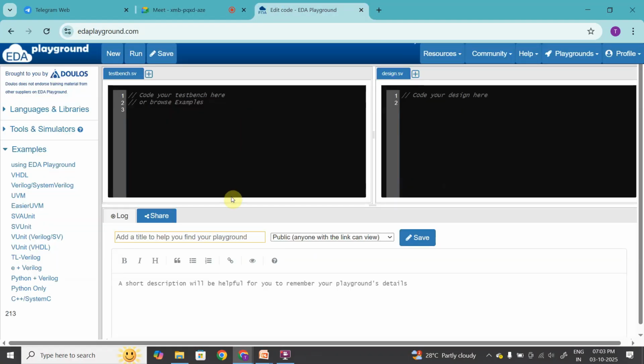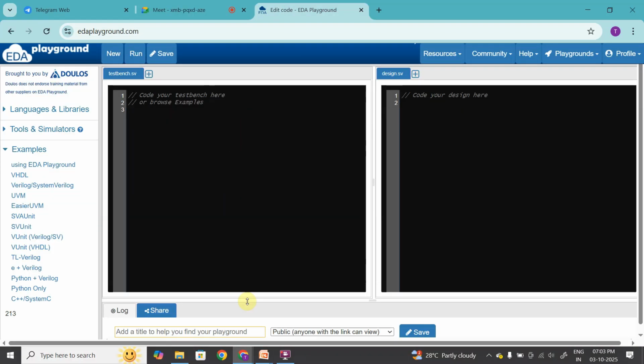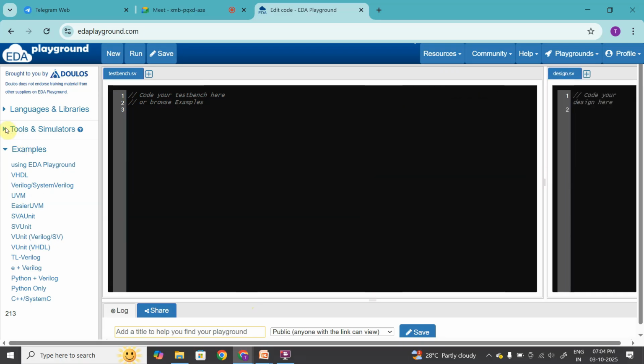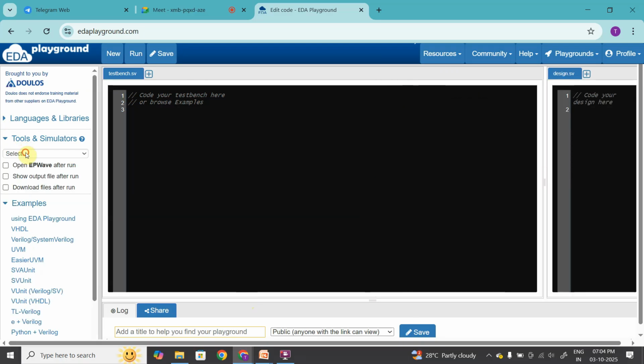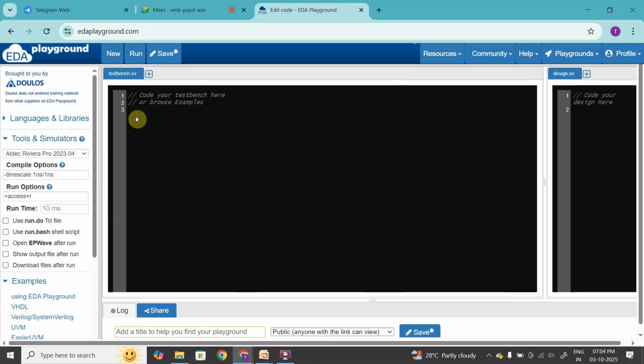Now, let us try to understand this with some examples, and let us frame some cases here. Let me start with case number one. I'm using the EDA playground. Let me select the tools. Here I'm going to declare a module example, and in it declare a variable reg a, without initializing. Within an initial begin-end block, which we haven't discussed yet but will discuss, we simply write a is equal to 4'b0010.